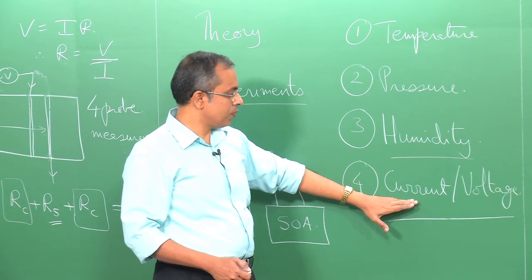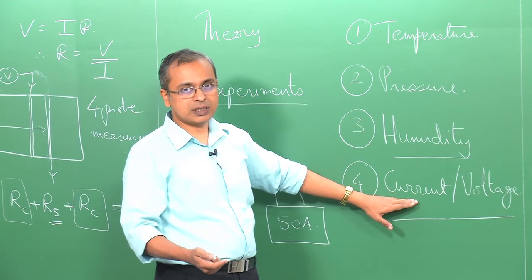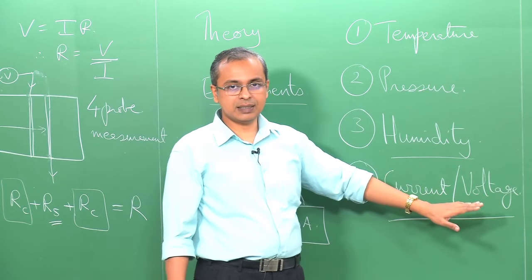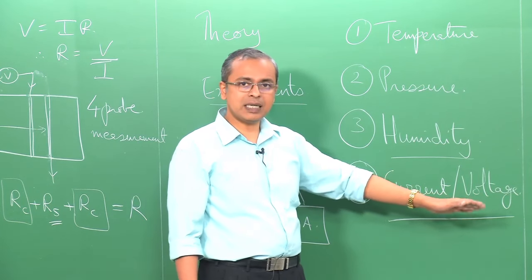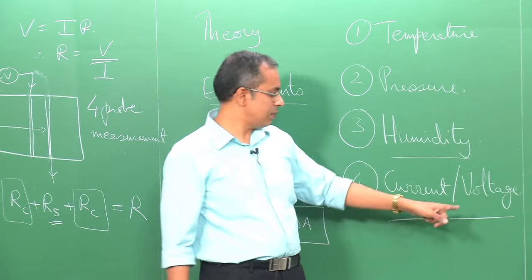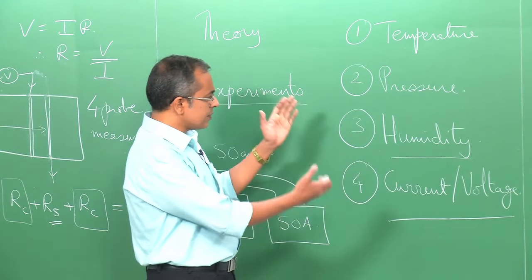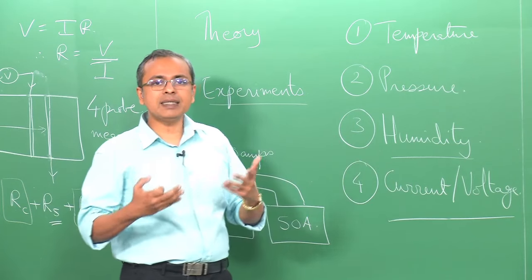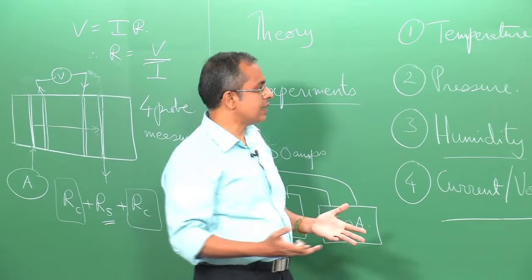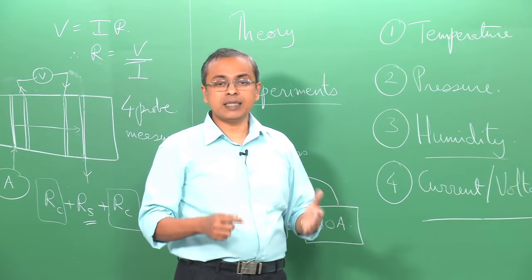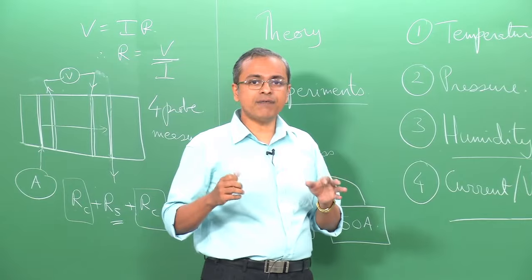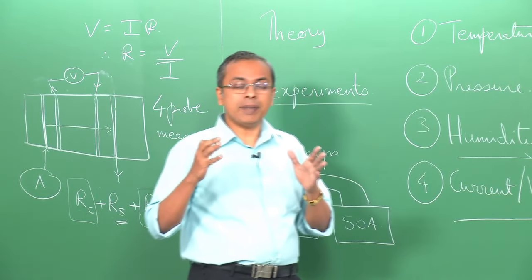Based on how you measure your current, you at least need to cross check the value of current, and the location where you measure the voltage could change the voltage, and may not change the voltage, but it will change the significance of the voltage because that is different. So, I have just looked at some common quantities here that we would typically measure, and the main thing that I want to convey is this idea that in all experiments there is room for error, okay, there is scope for error, and we have to as experimentalists pay attention to it.